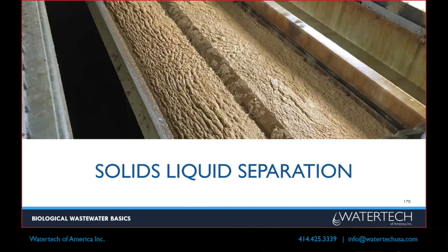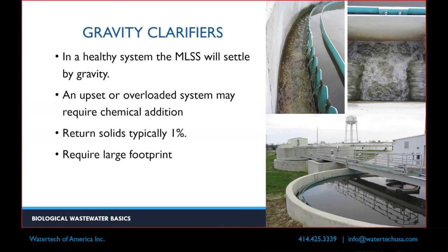Yeah. I won't spend a ton of time on this because Chris went into this in quite a bit of detail, but solid liquid separation, this is the important part. Once you've done all the hard work of treating your water, you want to make sure that you separate all the solids from the clean water so that you can discharge it. So if you go through all that work to treat it and then you have solids flowing over your weir, you're going to violate your permit, and you did all that hard work for nothing.